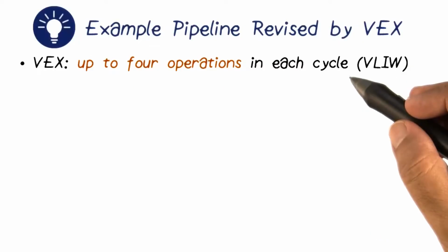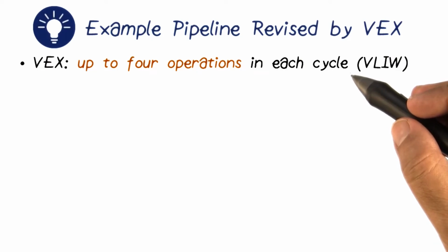Let us now understand a different type of instruction level parallelism which is exhibited by our VEX architecture. The VEX architecture implements a different form of instruction level parallelism called VLIW, in which multiple sub-instructions are packed into one which execute in parallel. VLIW is called Very Large Instruction Word. There are major restrictions on which sub-instructions can execute together in parallel in VLIW. The instructions should not have dependencies, nor should they share resources.